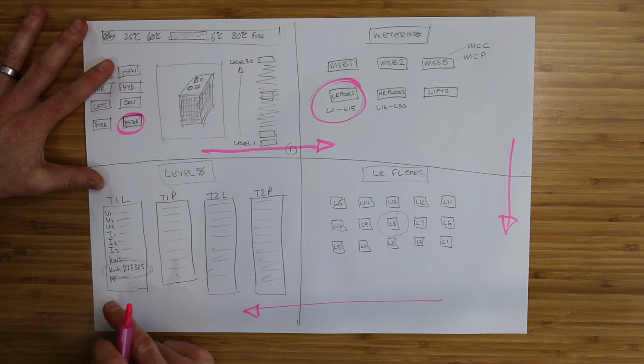Now keep in mind that there's 200 electric meters spread across, let's say, 50 different graphic pages. So let's run through the general process on a new construction project. We've got 200 electric meters. So the BMS design engineer does the design, creates all the meter schedules, and does all the network drawing design.